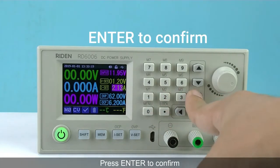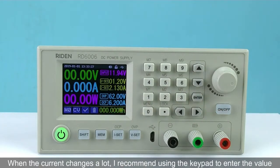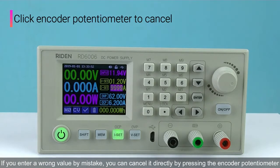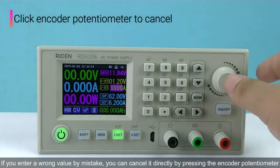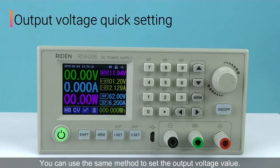Press Enter to confirm. When the current changes a lot, I recommend using the keypad to enter the value. If you enter a wrong value by mistake, you can cancel it directly by pressing the encoder potentiometer. You can use the same method to set the output voltage value.